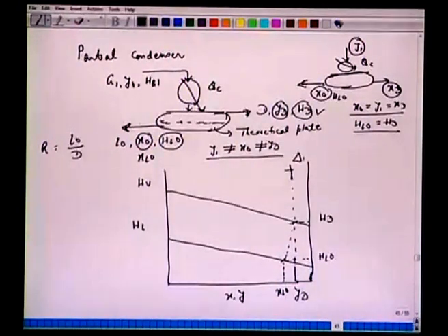That was our differential point, equivalent to this Q prime, which equals QC plus HD over D. This is the hypothetical stream which has a molar flow rate of D, but has the enthalpy of QC plus HD by D. So this difference point is fixed here, and the first thing we must note is that now we have to find the reflux ratio, which is defined as L0 by D.